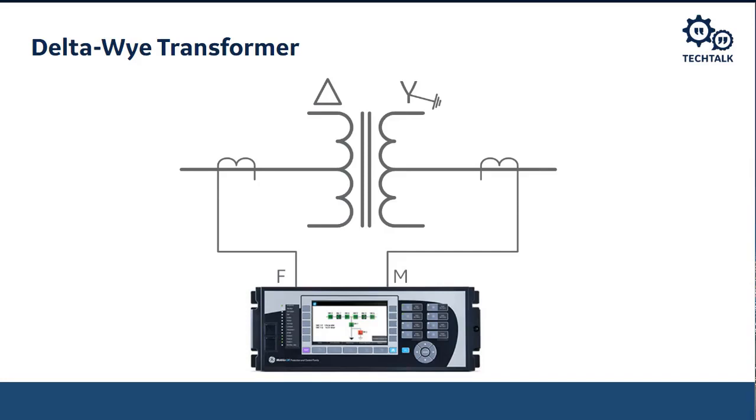We've got something like 13.8 kV or 12.47 kV on that transformer secondary, which is on the right side, which is the side that is connected in a grounded Y. On the left side is a 230 kV transmission system that's connected in delta. Remember, we connect that in delta, we intentionally do this, so that we can block those zero sequence quantities from our transmission system. We don't have to coordinate with them.